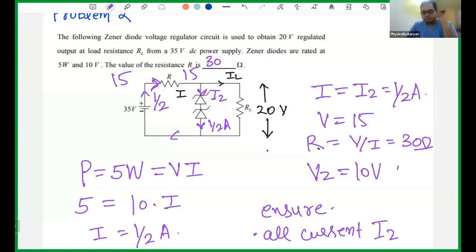Yeah. So if it flows, then your lower resistor will also work. So we are finding the maximum. If I put this much resistor, there is no chance of burning. Obviously, in most cases, current will come, and it will flow through the Zener and also through the load.